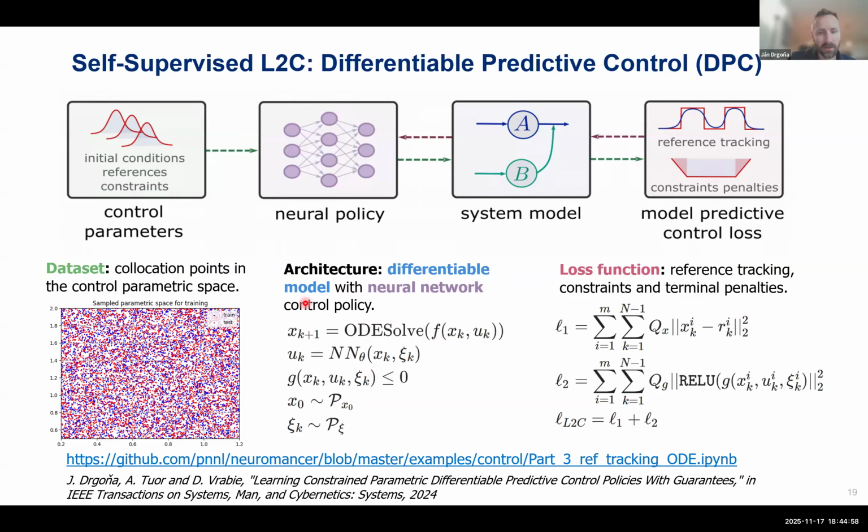And what you are constructing here is basically a closed loop dynamical system that you are evaluating over a distribution of parametric scenarios and initial conditions. And now you are obtaining trajectories over a finite horizon because we are doing these multiple rollouts over n steps forward in time. And this allows us to compute the stage cost and the penalties on each stage of the horizon, and do this empirical risk minimization training the same way like we do in learning to optimize and PINNs.